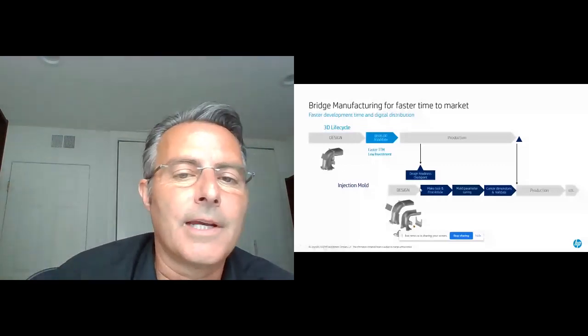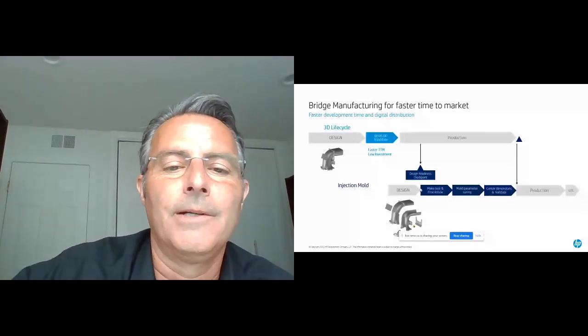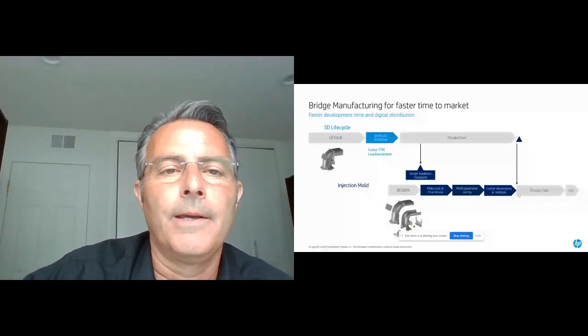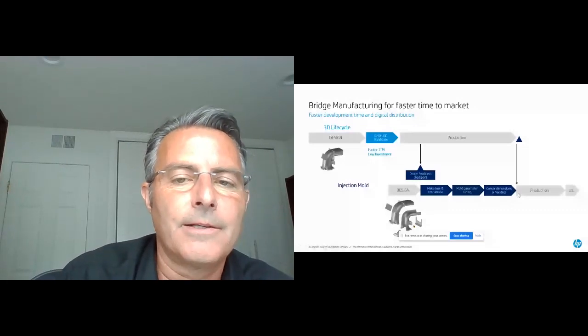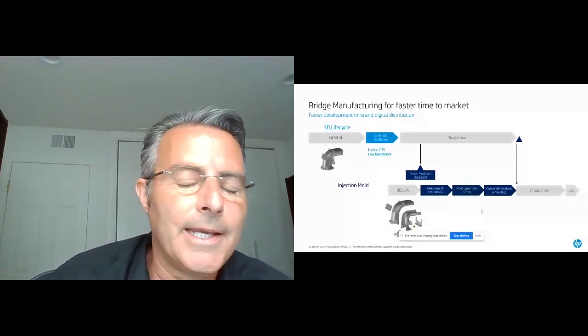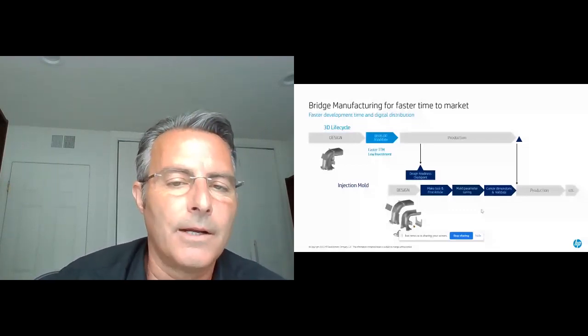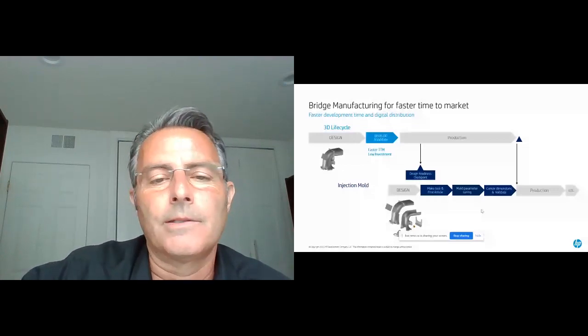Why do you launch the injection mold? Because the cost efficiencies of injection molded parts is phenomenal. When that mold is ready, you switch production to injection molding. This allows people to get to market faster for any given number of scenarios. One could be technical challenges. Another could be you just want to delay the investments in tooling.